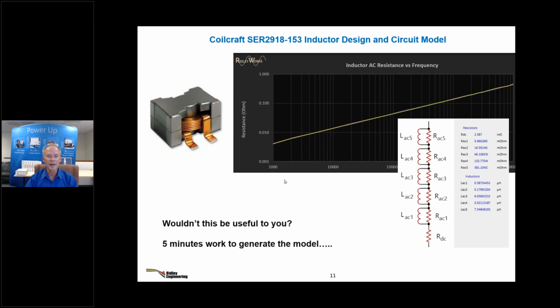Helical foil with 1 layer but thinner copper. No, it doesn't help, because thinner copper will just raise the resistance. So you just end up with less conductor at all frequencies. So the whole curve will shift upwards if you use thinner foil in a helical inductor. Now this particular Coilcraft inductor, they could have made it thicker, but it gets to this capacitance thing again. If you use thicker foil, the windings are crammed against each other and then the capacitance goes up quite a lot. So the resonant frequency goes down. So you've got this trade-off.